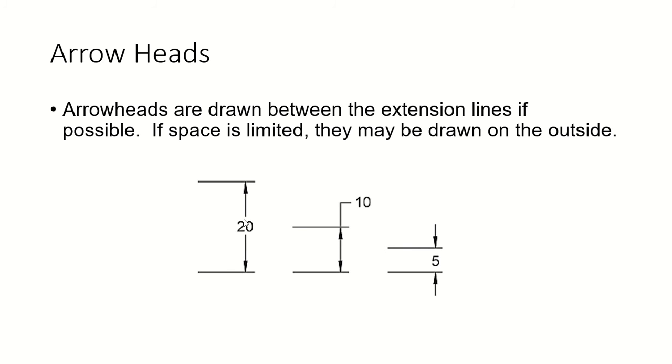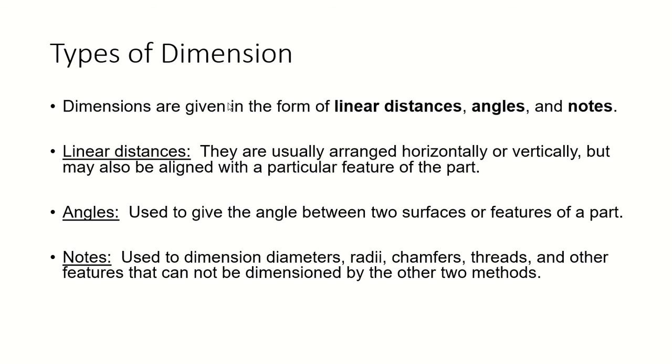See how different we put the measurement right in there. We put the measurement outside because of the space limit, even limited space right here, so the arrow's outside. Because if you put the arrow inside, you'll be getting head to head. So it's better to show your extension lines with the arrow outside for limited space drawings. Then we'll get into types of dimension.